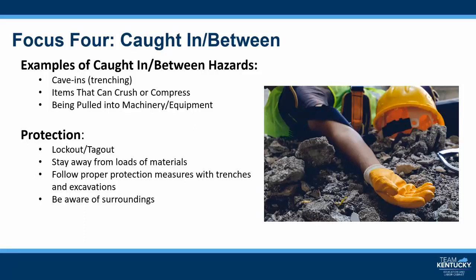Events that should be classified as caught-in hazards in construction include cave-ins with trenching, being pulled into or caught in machinery and equipment. This includes strangulation as the result of caught clothing in running machinery and equipment. Being compressed or crushed between rolling, sliding, or shifting objects such as trailers, materials, concrete, dirt or gravel, or between a truck frame and a hydraulic bed that is lowering.